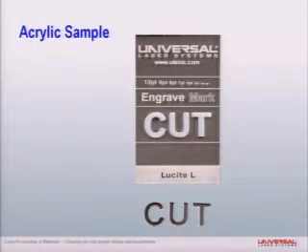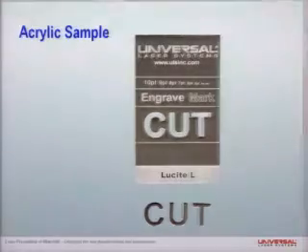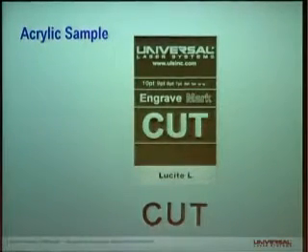Here's just a sample. This is a piece of acrylic. It's got a black backing so you can see it. But it's marked here. This is a raster mark. More raster marking going all the way down to 2-point text. This is a raster mark and a vector mark where we just kind of trace the outline of the word mark. We cut out the word cut here, and here's the part that was cut out. But all these are based on the materials database settings that are a result of that characterization that we went through in the lab.